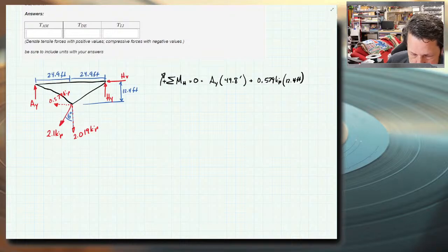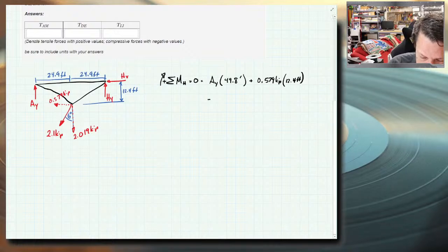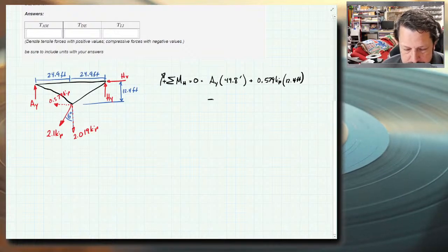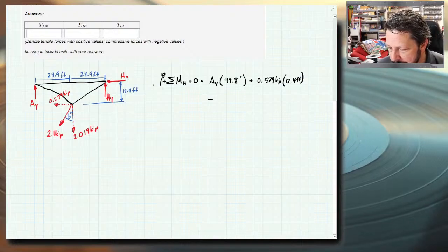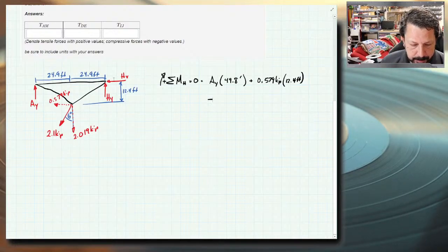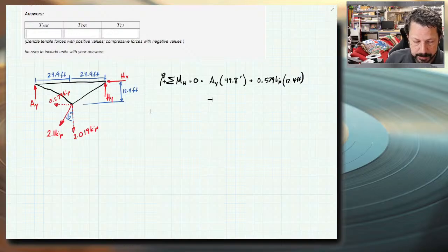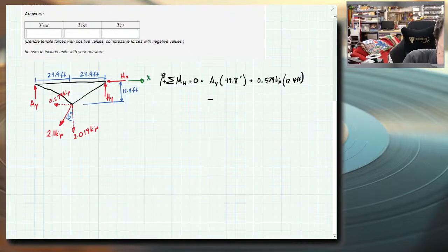We need to do the vertical component, writing our moments about H. It's going around counterclockwise, so I'm going to put minus on it for my sense. I said positive was clockwise. Why is the x and y component of the force not negative? They are, but if I was writing a summation of forces, then I would need negative and positive signs, because they're going left and going down, which, I didn't draw it on here, but normally x is positive when it goes right, y is positive when it goes up.